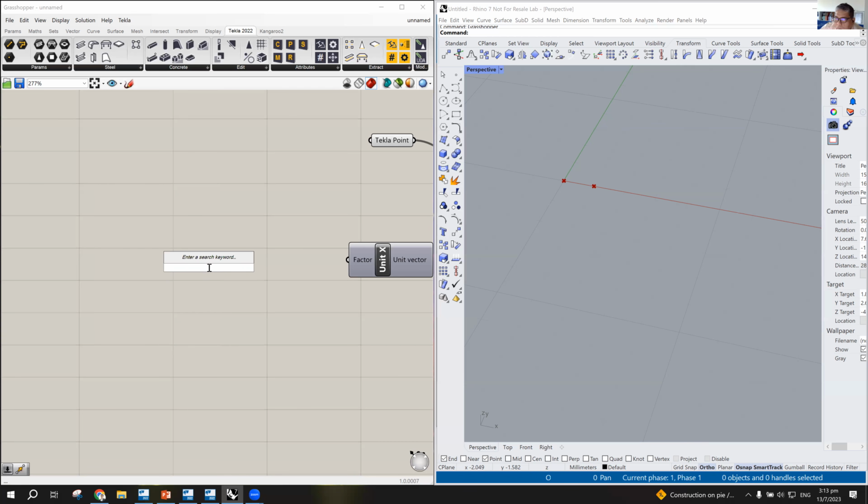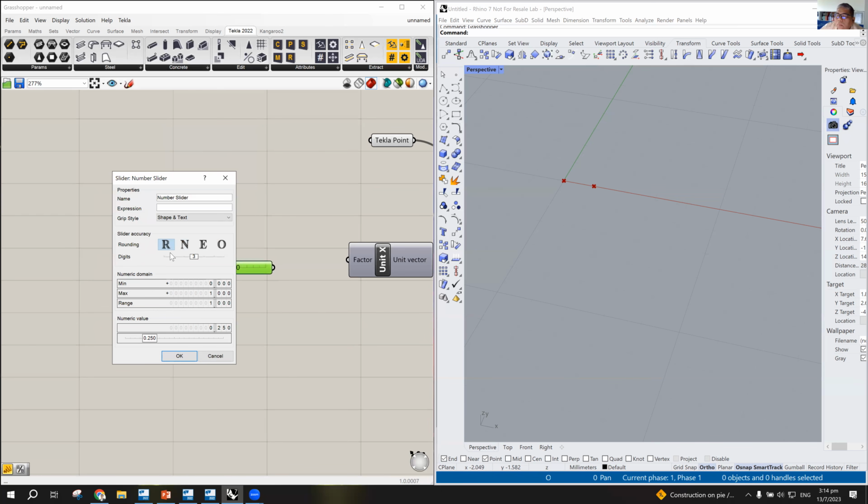Let's say, for example, the value that I want to key in here is 3 meters. 1, 2, 3. See? If I type here 3 meters, automatically it will adapt as a number slider. So again, you don't need to type slider here. This is the basic one: you type the number slider and then put in the value, the rounding and all the minimum and maximum.